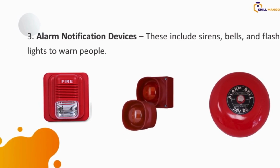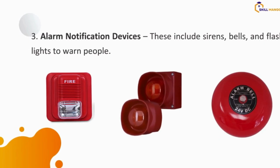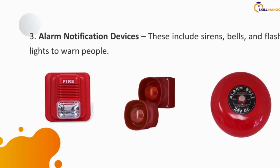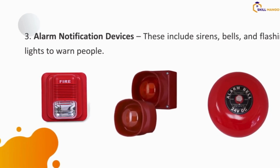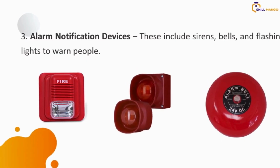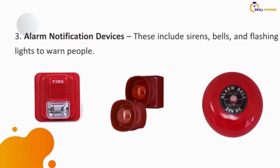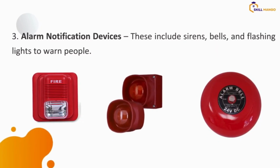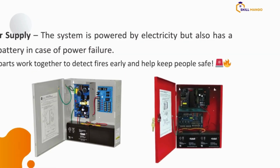They are usually 24 volts, and some are 12 volts actually. But it's better you maintain your 24 volt DC because your panel is 24 volt DC. So all the equipment you're going to be using on the chain is 24 volt DC. All right, so this is very important for us to note down when we're doing our deployment and installation or maintenance or even troubleshooting. You have to be sure that you check your power ratings of your devices before you continue.